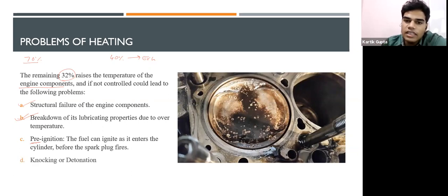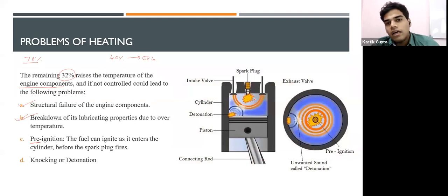This could happen if internally, before even the ignition takes place because of the spark plug, the components inside this area, the clearance volume area, exceed the limit at which combustion takes place, because already the temperature of these particles is a little high. If that case takes place, then we have ignition before even the spark plug has fired. Now that is known as pre-ignition.